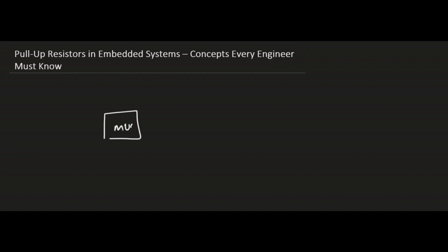Does a microcontroller unit pin randomly change state from 1 to 0 or 0 to 1 even when your code is perfectly working fine? This is not a bug. It's not a bug. It's a problem of a missing pull-up resistor.